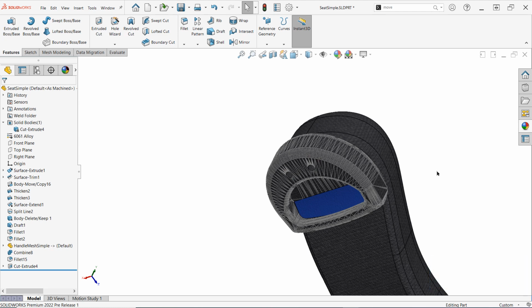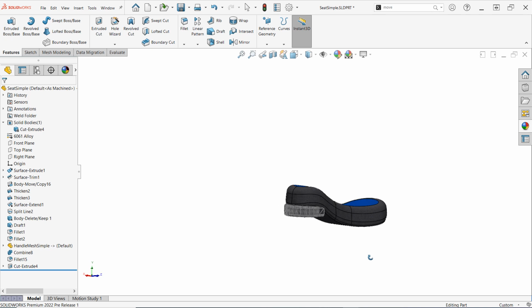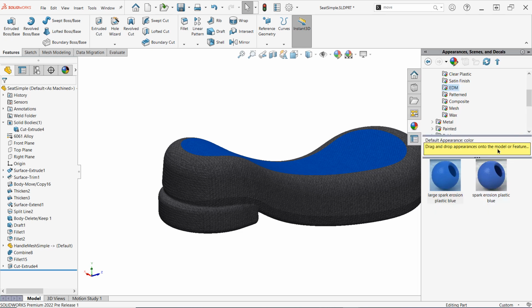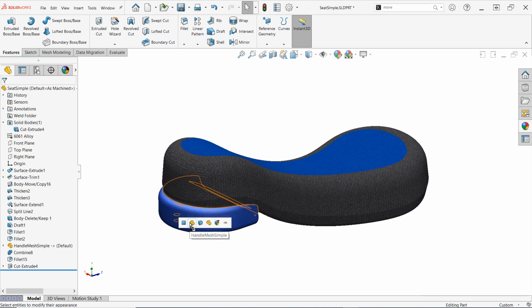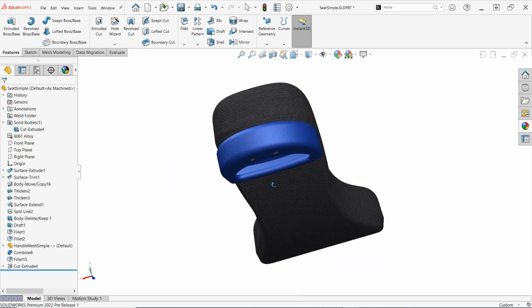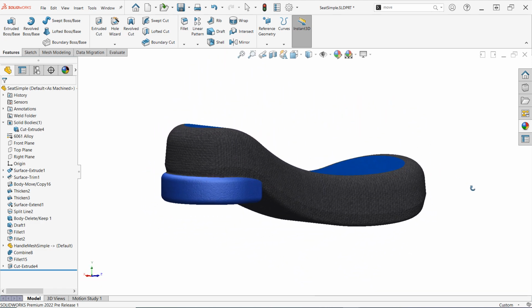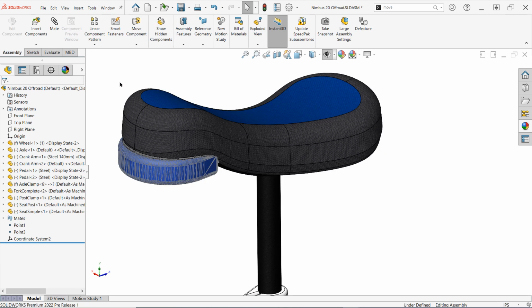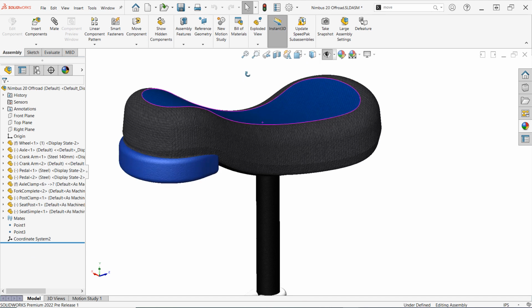Now, a couple of important things to keep in mind. Mesh files are great for many applications, primarily if you intend for your final product to be 3D printed. However, meshes are typically not suitable for use in CNC or CAM operations, and they aren't particularly compatible with SOLIDWORKS drawings, as you can't reference meshes to create dimensions or other annotations. So while this hybrid mesh modeling approach may be very valuable for some users, please proceed with caution and thoroughly test this workflow for compatibility, especially if you're working in a production environment, and also understand that there are some limitations to this strategy.